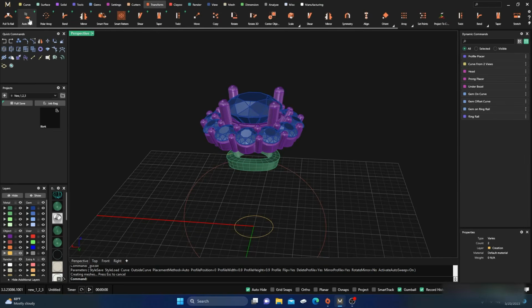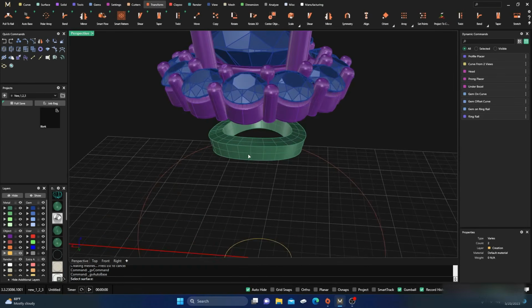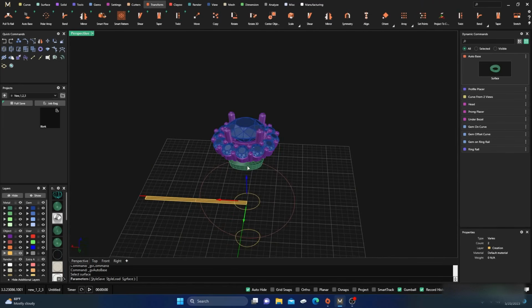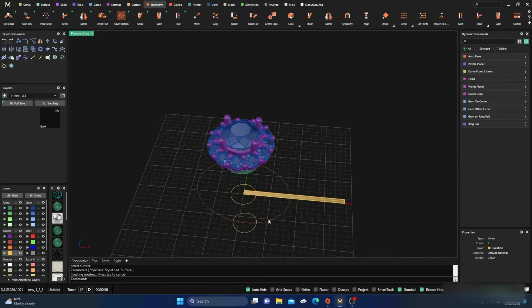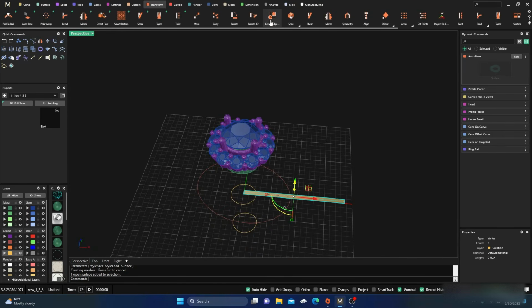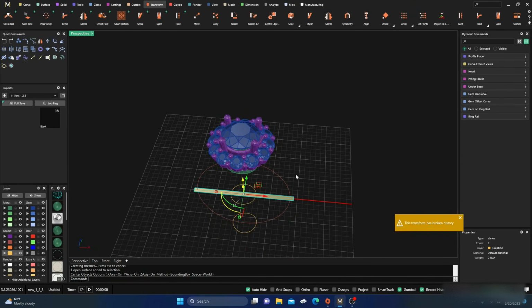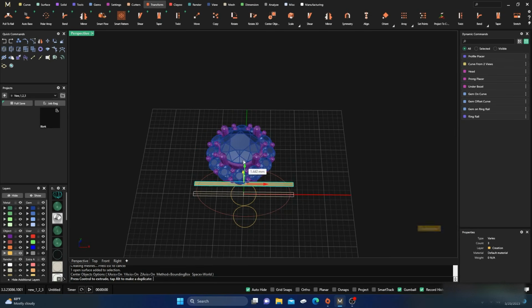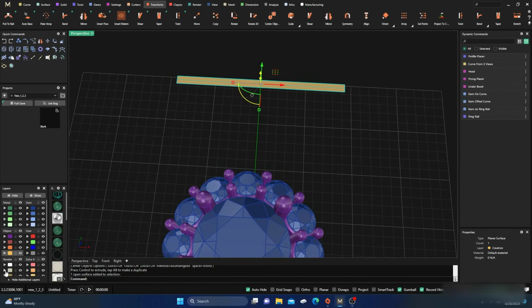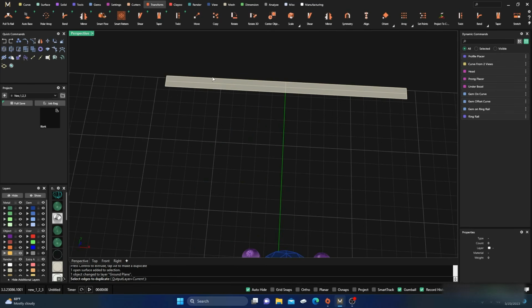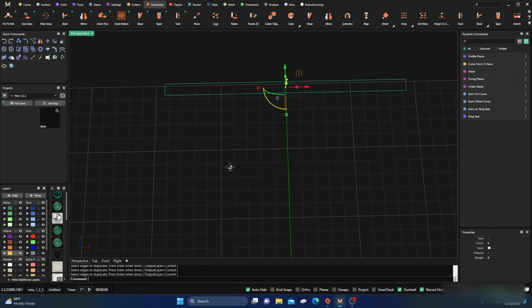So we're going to go to transform, select auto base, select our surface. It'll be that surface there, the outside facing, and we're going to hit enter, and I'll swing that around, and then I'm going to take that, and since we're here, I'm just going to go ahead and center it. It doesn't matter about this breaking history, and then we're going to take that up there, and I'm going to switch it to a little bit friendlier color, and then I'm going to do my deal that I always do, and select all 4 edges and hit enter, and then I'm going to turn off that surface.